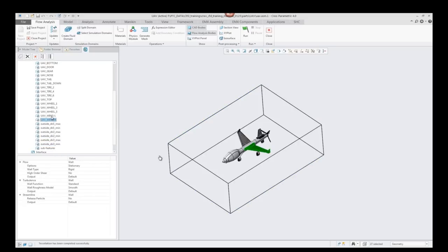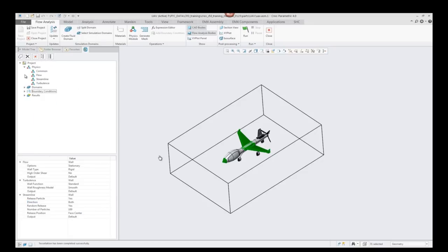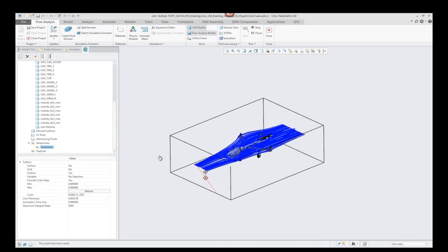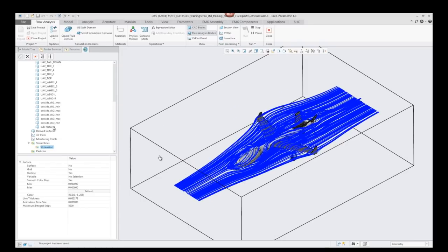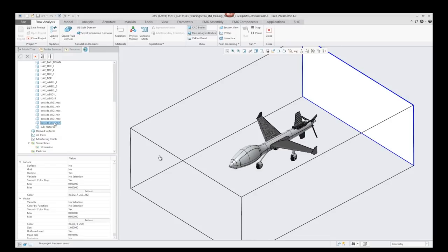So the remaining 5 or 6 faces of the hangar, what I did there is I said apply the same velocity going towards the rear of the plane, and now I've picked the wings and the nose cone, and those alone for releasing the smoke particles. Now I've hit the run button without doing the meshing up front. It goes and creates it for me, and immediately we can start to take a look at the streamlines, and this is prior to the experiment actually having finished.